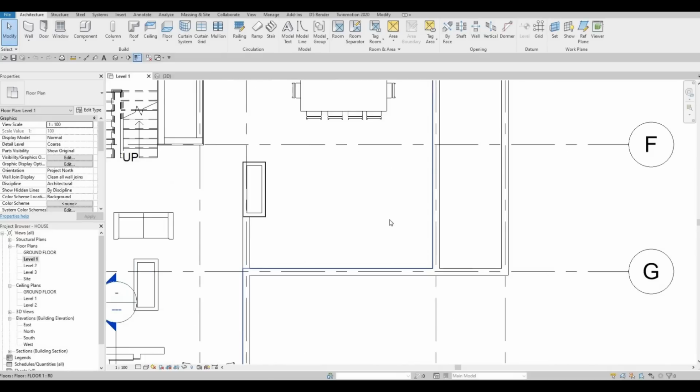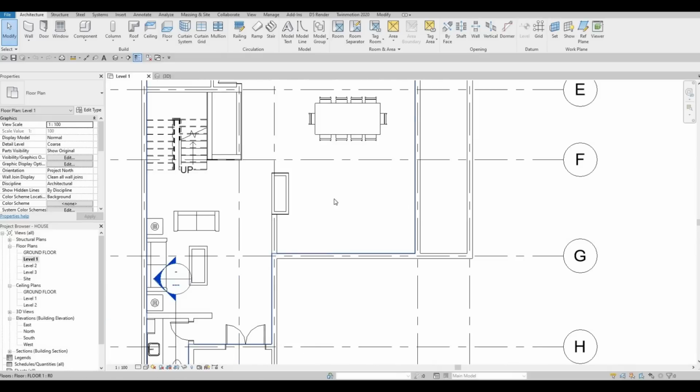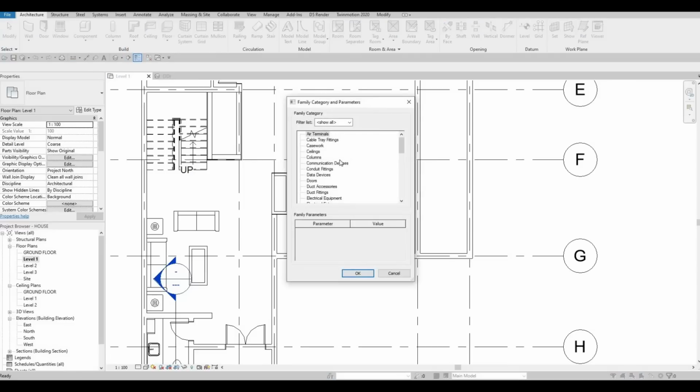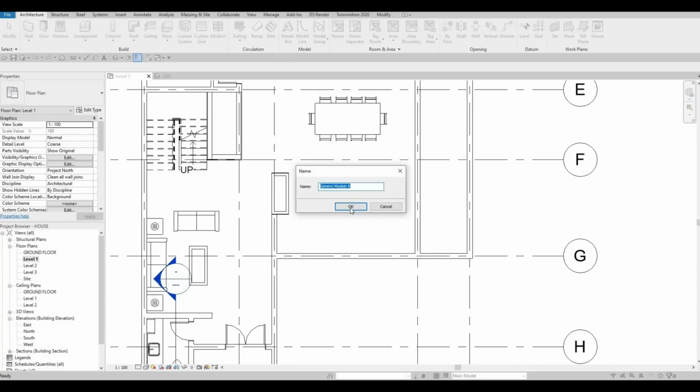What I want to do here is to have an L shape and maybe a bar here or an island. So yeah, might as well put an island here and then an L shape on this area. So now what I'm gonna do is go to our architecture and then model in place, drop down interior component so that you can see the model in place right here, and then now scroll down to go to our generic models and then press OK.